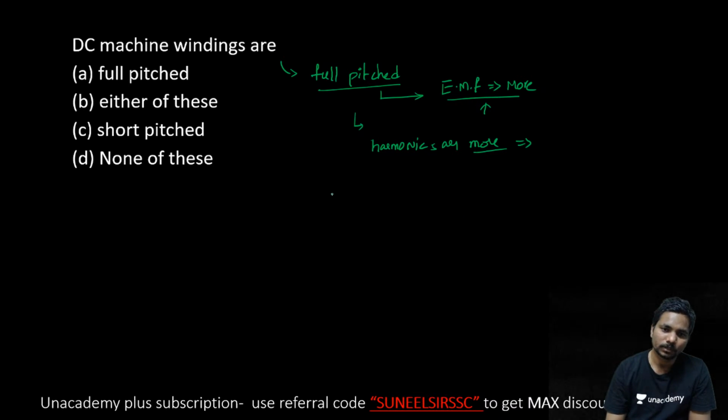And in case of AC machine like synchronous machine, we use the short pitch, because in a synchronous machine harmonics are more dominant.